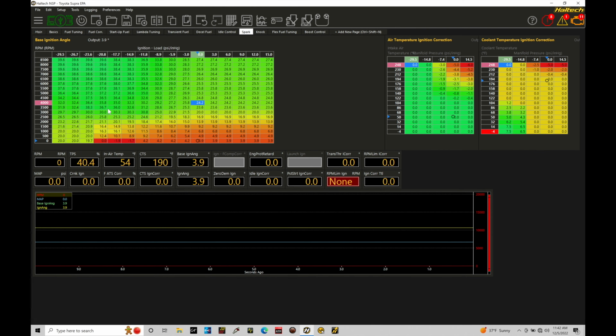Going too low, the engine's power and torque production will suffer. It'll feel sluggish, it won't feel smooth. Too high, you'll run into knock or pre-ignition. We could damage the engine from uncontrolled cylinder pressure, uncontrolled combustion. So we want to be specific with this.